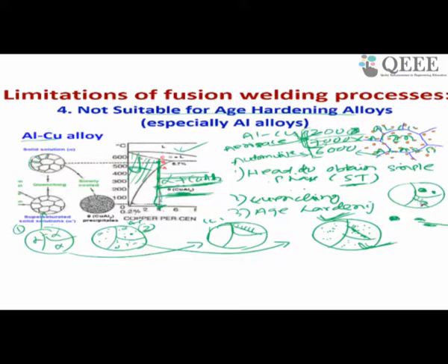In that case, what will happen? The dislocation cannot break this big particle, it can bypass it. This is called bowing, and again it will move. So in this case, strength will again reduce.